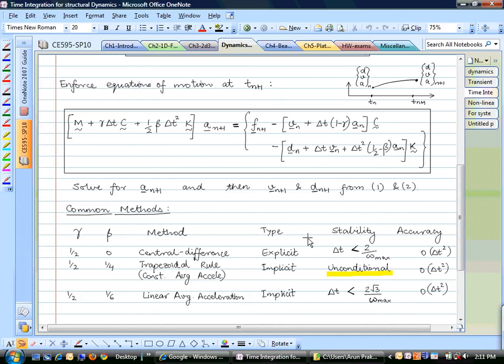So what will happen is you apply a load and it will oscillate, and the oscillations will damp out. So it will converge to the static solution. That's what this central difference explicit method does, and that's what Abaqus uses for this.